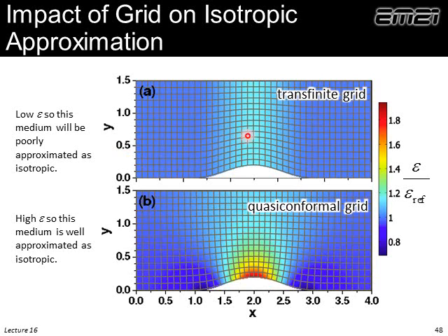Notice again that we have a big wave up top and a smaller wave down bottom. So less anisotropy with a high dielectric constant. We need more anisotropy for the low dielectric constant. And it's probably more difficult to get anisotropy than it is to get a high dielectric constant. So that's preferred for this case.